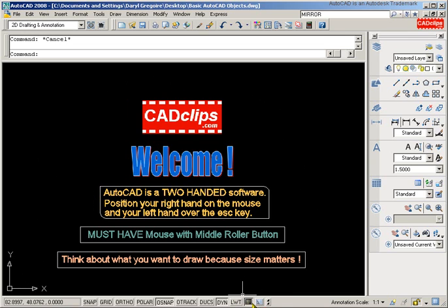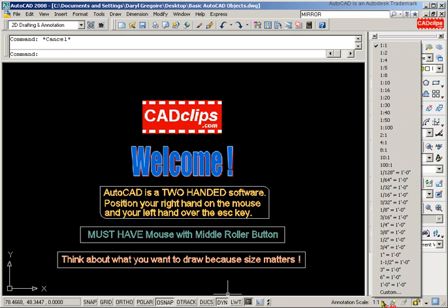And the last thing, as we get over here, we're going to start to see some buttons in here we'll talk about in our advanced lessons on using paper space, some paper space buttons over here. Annotation scale, which was brought in 2008, which is super fantastic. Now you can set your annotation scale. This saves me a great deal of time trying to teach you about annotation scale because now it's all built in. So these are typical scale factors. 1/4 inch equals 1 foot, 3/16 of an inch equals 1 foot, etc. Some metric scales up over here. Okay, so imperial and metric scales, you can even create your own custom scale.